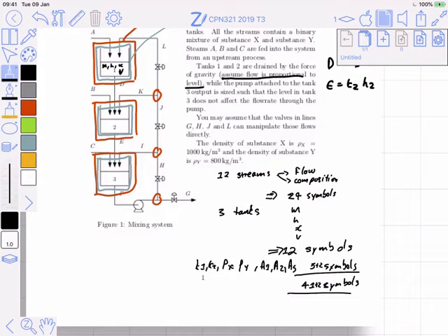But I want you to understand what that means. The mass balance does not reduce to a volume balance. That is a consequence of specifying ideal mixing. So it's kind of a different thing. I personally don't think that you really need to go there because it is straightforward enough to simply state the model in mass terms.